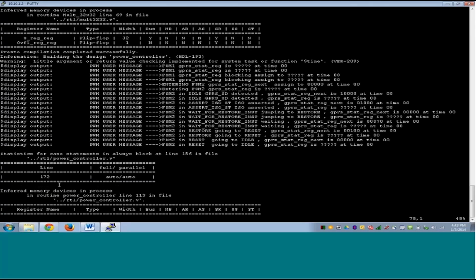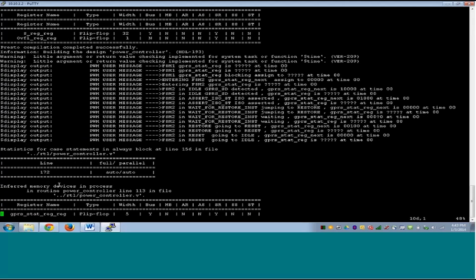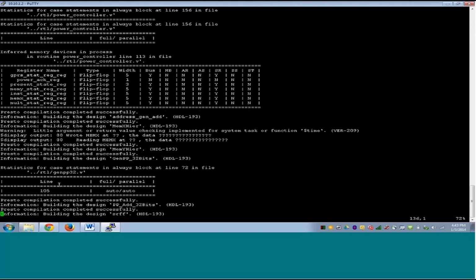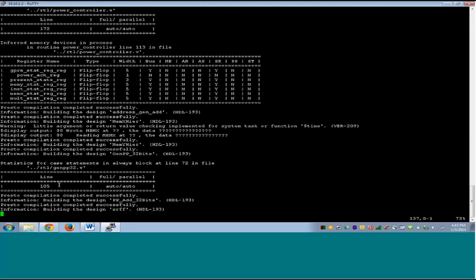It also gives the display outputs, which are don't care for synthesis. $display, $time, etc. are simulation constructs used in the RTL, but DC ignores them. It just gives the display output, but it doesn't affect the quality of synthesis. When you write code, you should try to only use synthesizable code. If you want to use non-synthesizable constructs like $display and $time, you could do that, but use macros like ifdef to make sure that they are not read during synthesis. It's a good practice.